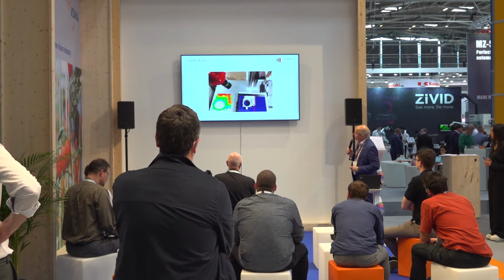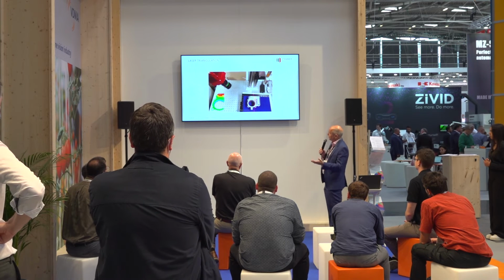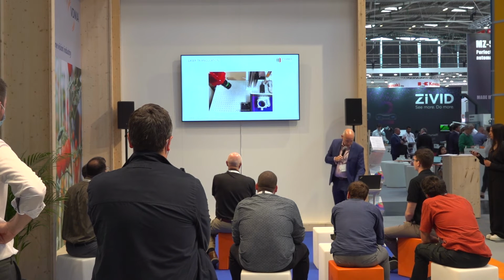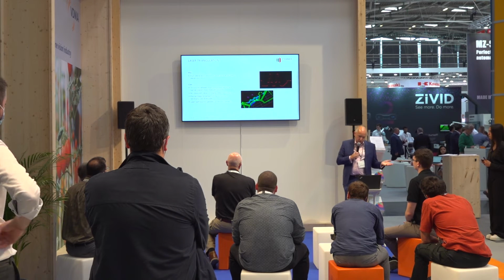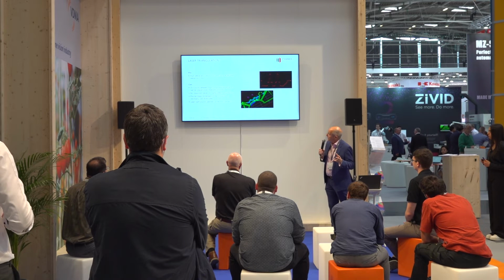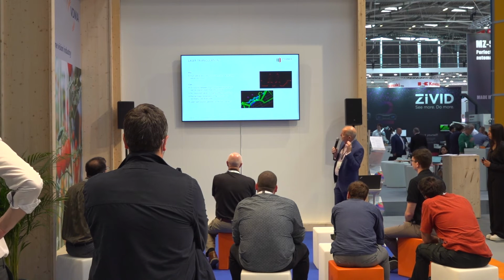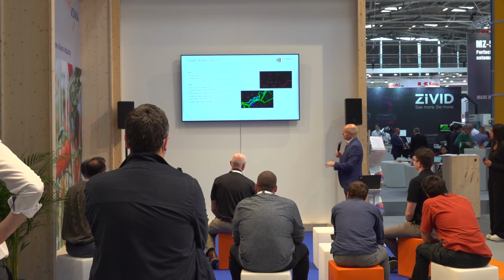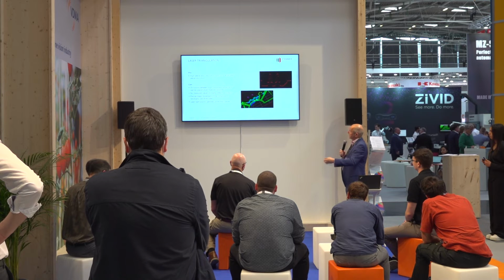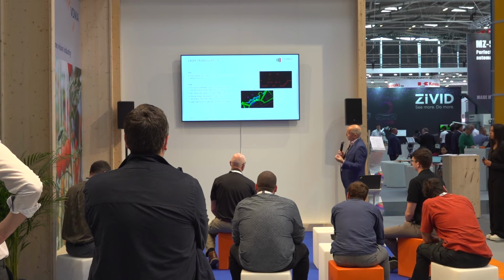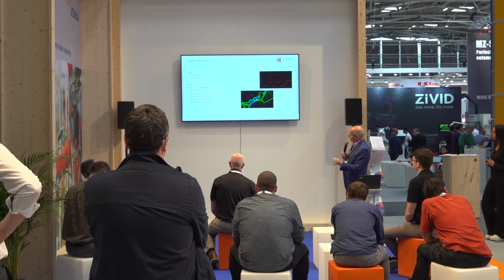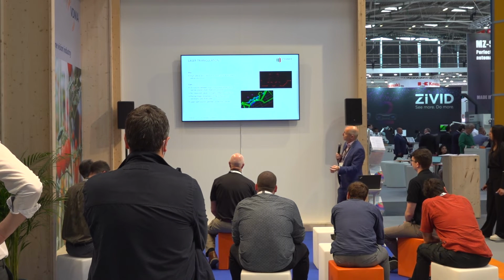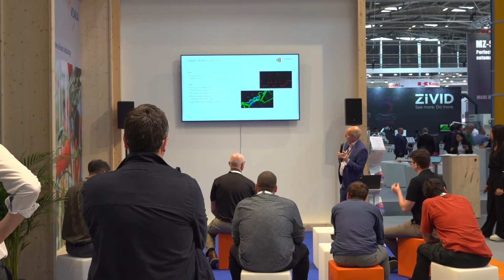So now back onto that image that I showed you earlier, what we're actually then able to do is build up this 3D height map based on that laser coming through. We also have challenges though. So what sort of resolutions can we come up with? Obviously, laser triangulation is high resolution, so 4K is pretty typical now. 4,000 pixels across. If you're triggering with an encoder, you can build up really high resolutions. But we have to deal with occlusions, and then if you have highly reflective surfaces, you can get errors. And I'll come on to how to deal with that in a minute.